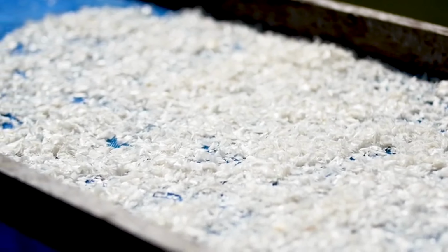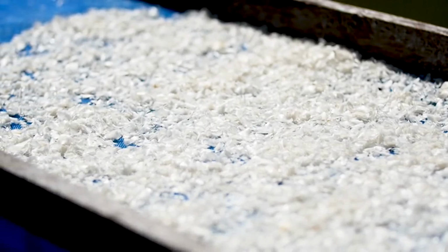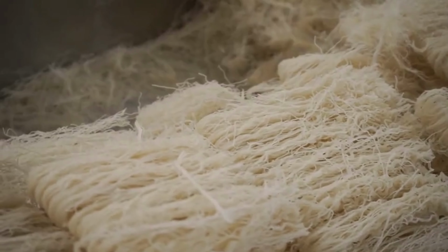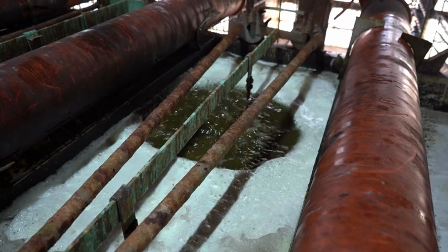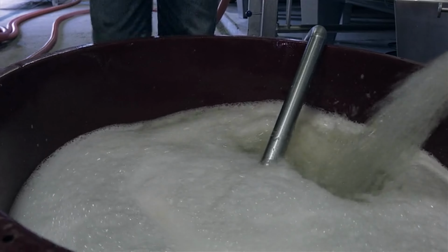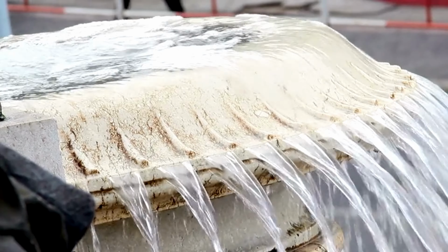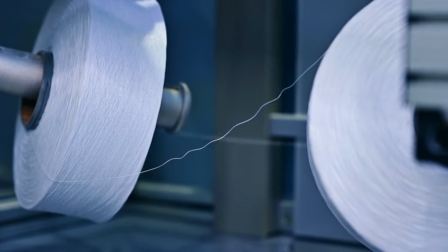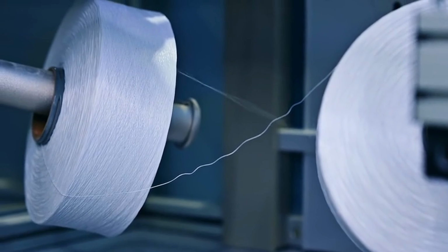C. Recycled paper processing. Paper is shredded, mixed with water, and treated with surfactants to remove ink. Fibers are cleaned and refined for reuse. 3. Pulp refining and cleaning. Before paper making, the pulp must be refined and cleaned to ensure quality. Refining, beating. The pulp is passed through refiners that break down fibers to improve bonding. Refined fibers create stronger, smoother paper.